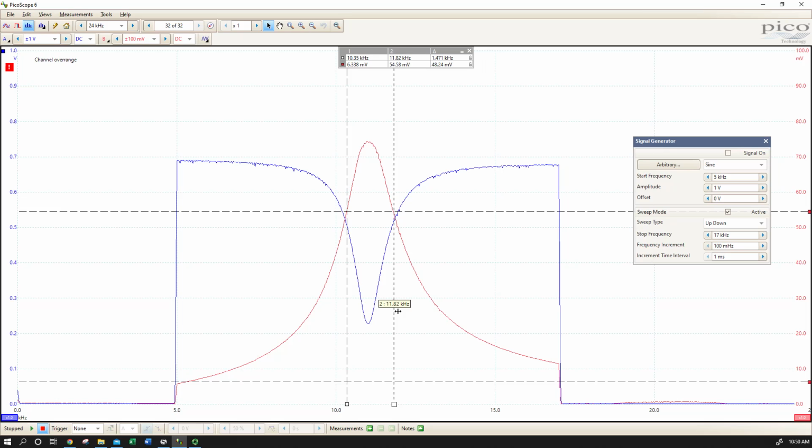maybe a 50 ohm. Of course, I would have been limited by the output impedance of my AWG ultimately, but I could have used a bigger inductor or a smaller capacitor if I had had one, or used a series parallel combo to achieve that.